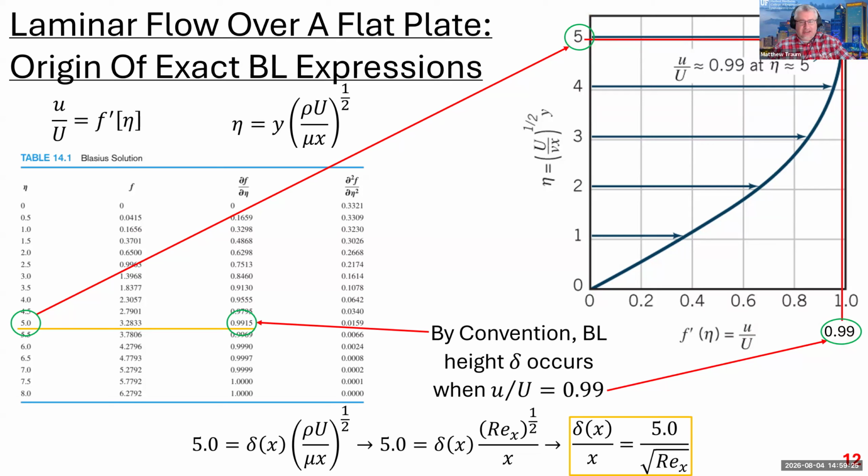And so you can actually see this. You can see it graphically here, but you can also see it in tabulated form. So this is the tabulated solutions to the Blasius equation. I will mention that there is no finite solution to the Blasius equation. It's solved numerically, but you guys have seen that done already, right? For things like temperature field and a flat plate, right? You just take the number of terms that you need to get the number of digits here where these numbers don't change for engineering purposes, and that's considered the solution from an engineering perspective.